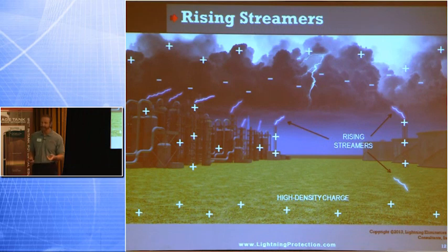Why is that important? All the standards that we use today for lightning protection, the most accepted standards that we see throughout the world, whether in the United States or in Europe or other parts of the world, are almost all the same with some slight deviation. The aim is to develop a very competitive upward streamer. For a lightning rod system, we'll talk about that in a minute, its whole mission is to be a competitive streamer generator. It wants to be the preferred collection point, using the facts that we know about lightning.